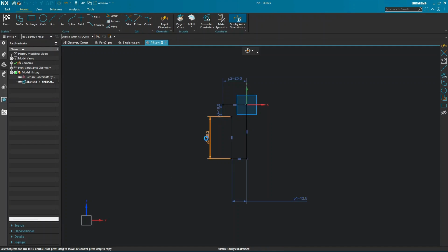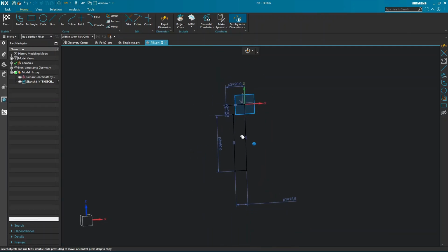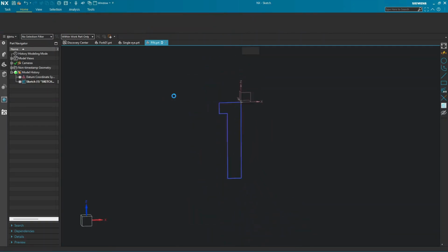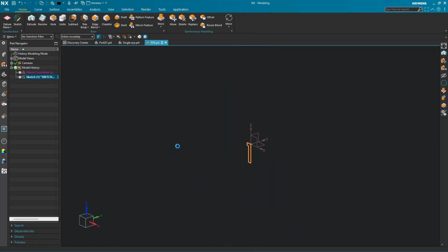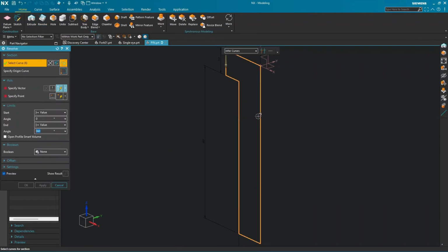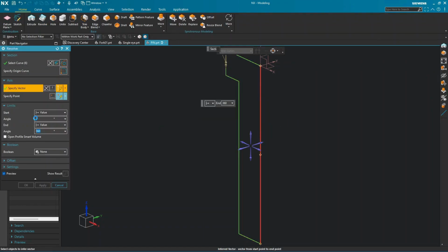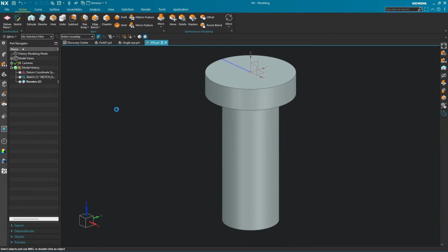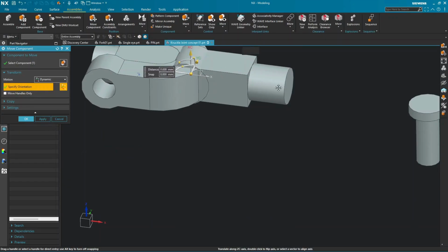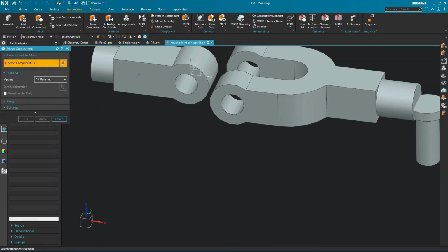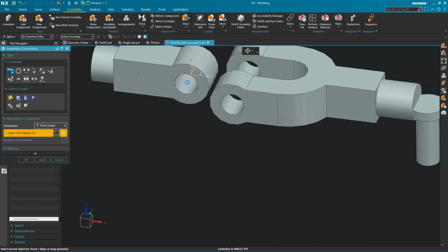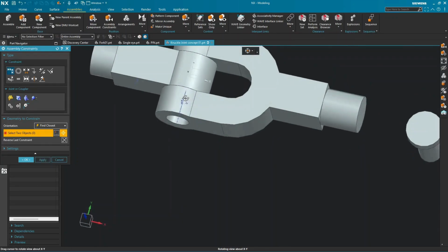After finalizing the geometry, I revolve or extrude the sketch to form the 3D body and then apply fillets and chamfers on the edges for better aesthetics and to eliminate sharp corners. This completes the knuckle pin, which now precisely fits through the eye and fork holes, providing the pivotal connection for the joint. Now that all individual components, the fork end, eye end, and knuckle pin, are ready, let's assemble them to form the complete knuckle joint.